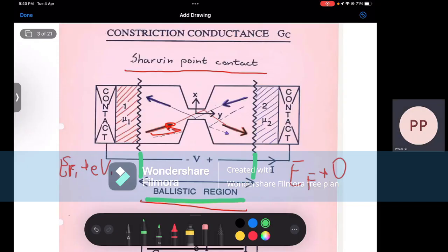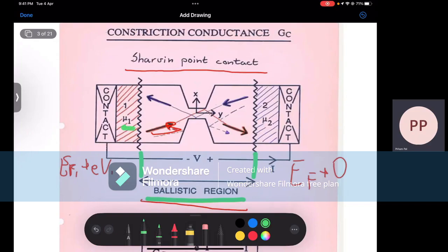And then to pass a current through the constriction, we better connect this constriction into an electrical circuit, which we can understand as having some contacts to the two-dimensional electron gas, hooked up to a battery. It will have a region next to the left contact, the first contact, where electrons will be equilibrated to some chemical potential, that's mu1.